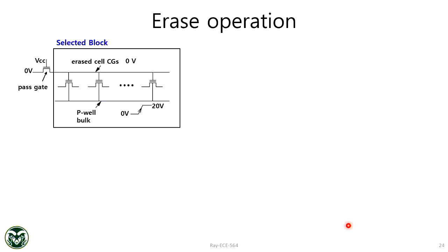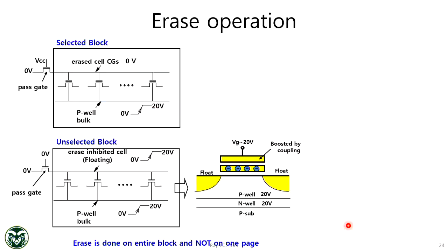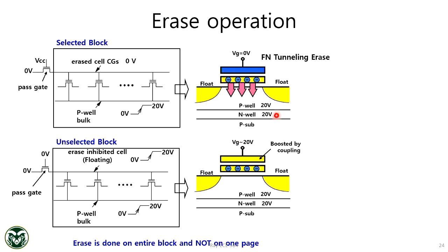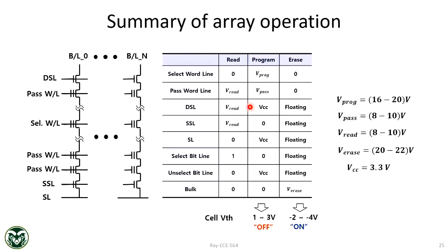So this is the final last thing about erase. Erase is all about putting high voltage on the bulk. There is no need for precise control or anything. You just put flash erase. Everything should be erased. So it's one step you can erase, but still it will take some time because you need to take out, right, all those stored electrons. So you need to give some time to erase the substrate voltage and allow those electrons to be taken out. So that's pretty much the last slide.